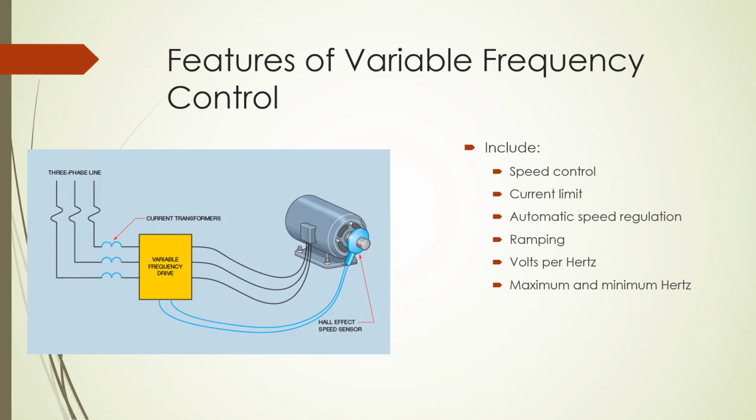We don't have to put in reactors or resistors in front of the VFD because the VFD is going to make all those decisions for us. So we just feed the VFD from a breaker, and we have the 1 or 3 current transformers to measure how much current is coming into the VFD. The VFD will do the soft start, will do the frequency control, and will also sense overload conditions.